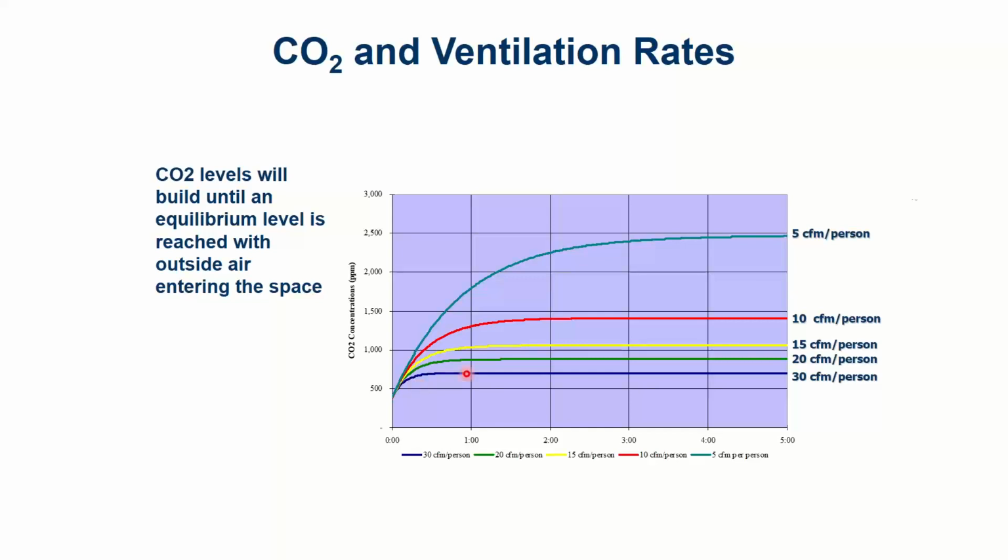However, when I put a CO2 sensor on the wall in the room to measure what's going on in there, that doesn't mean the CO2 sensor waits until things level off and then I react. Everybody piles into the conference room. The CO2 level is going to start going up. I don't wait till it gets to a really high emergency point and then do something. As I see it creeping up, I start opening the ventilation more.